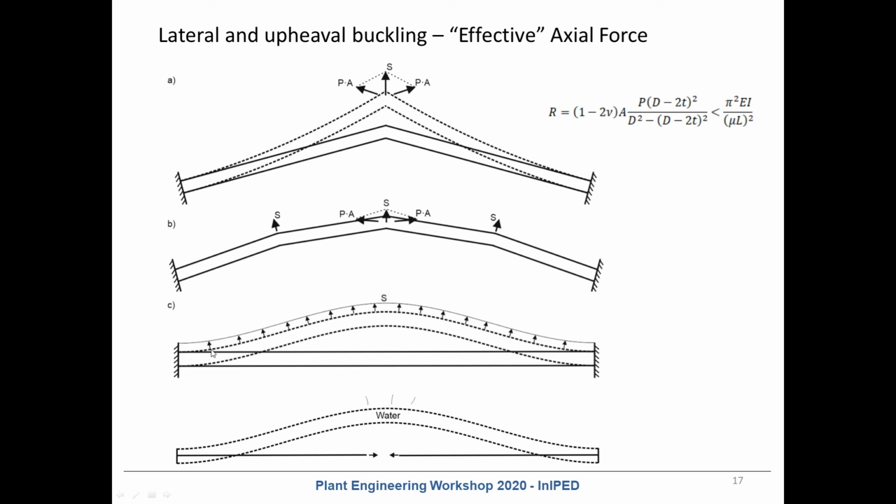And now let's imagine that we break the pipe into an infinite number of sections, and the pressure forces will produce a uniform load that pushes the pipe in lateral direction. So the pressure load tends to buckle the pipe. Another way you can imagine it is that the contents of the pipe, for example the water inside the pipe, work like a beam, and you compress this beam, and this beam is buckled under the compressive force.